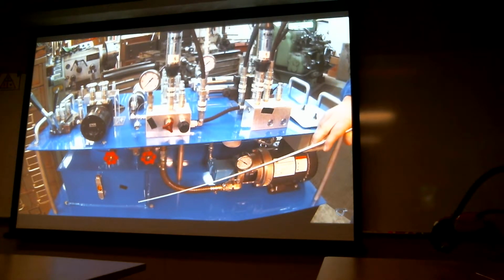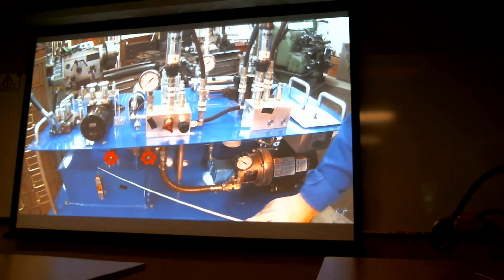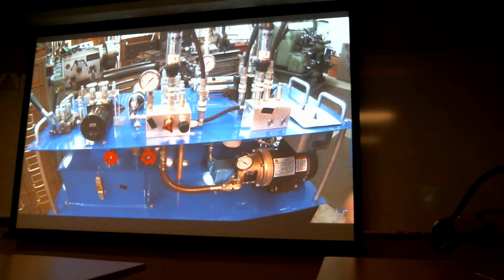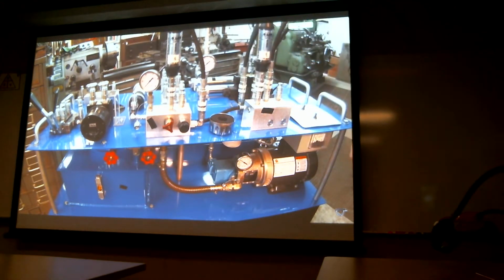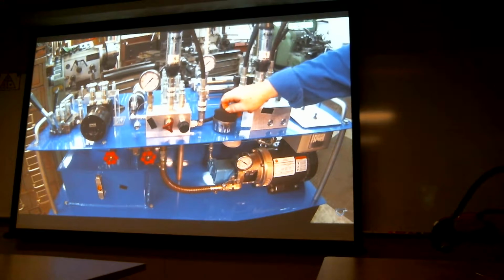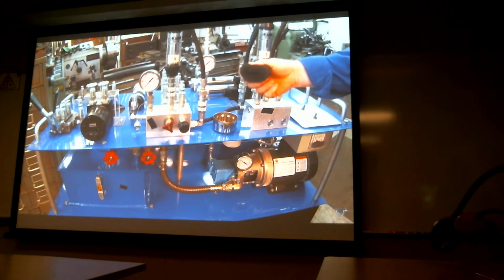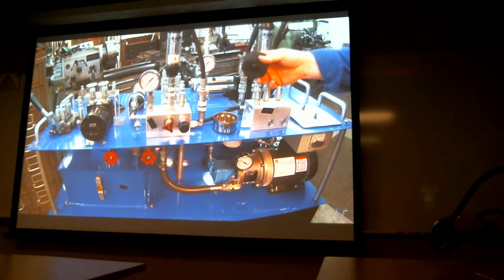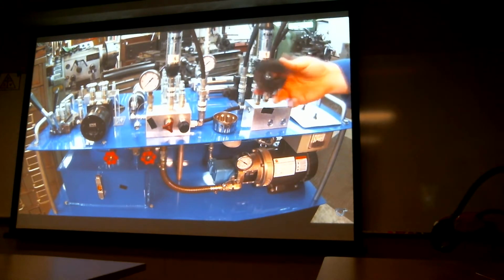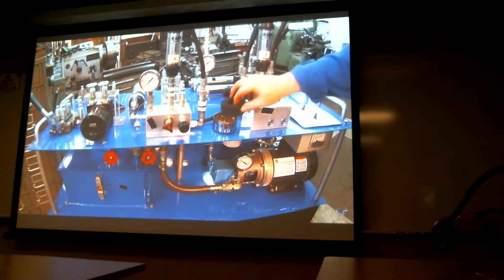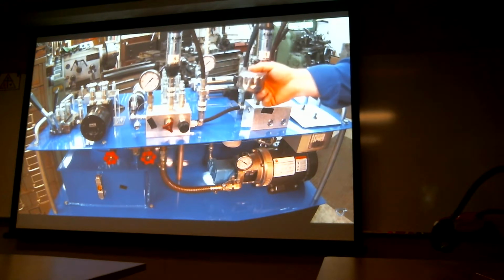All right, how they fail is leaks, obviously, which is a safety hazard. Also clogged breathers. There's a breather up here on top of the reservoir, and I've got one of these breathers taken apart so you can see what's inside of it. This is just a piece of foam. So you'll see those breathers are basically garbage, okay? They don't catch very much. The things I need to protect this pump from are down at the 3 micron level, and this definitely isn't 3 microns. So if you see one of these silver breathers on top of your system, it basically isn't doing very much.